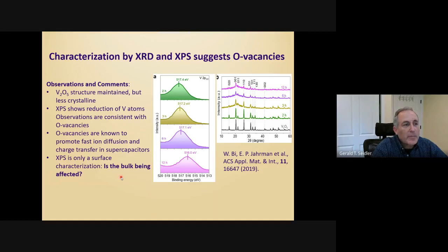For the X-ray emission spectroscopy measurements, you could go up to as much as a 4 kilowatt tube. The interior design of the tube changes in a way that you won't really get a 40 times benefit, but you'd probably get another 5 or 6 times count rate by going to the 4 kilowatt tube.